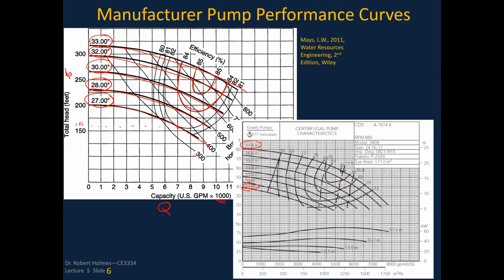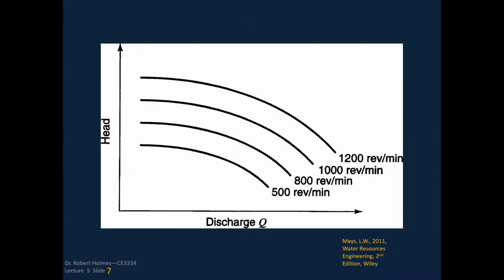and then superimposed on that is a net positive suction head required. And you can see these have values here of 7 feet, here's 10 feet, here's 16 feet. And then down here, we've got our values of the kilowatts required. Sort of the brake horsepower is shown here in this graph. And here's the kilowatts down over here on the right. And again, these are plotted in both feet and in meters, and you've got both meters cubed per hour and gallons per minute on this pump curve.